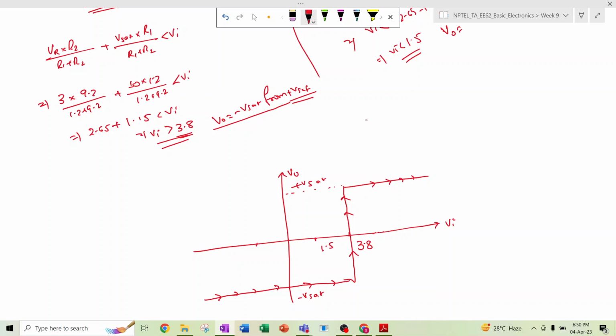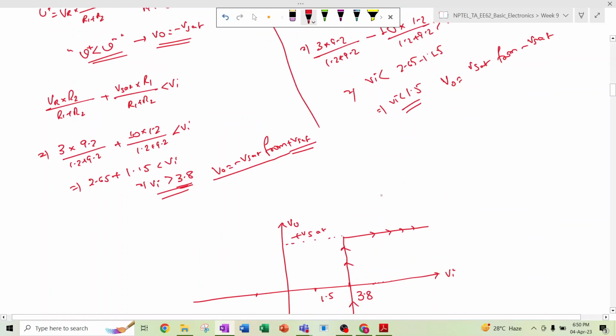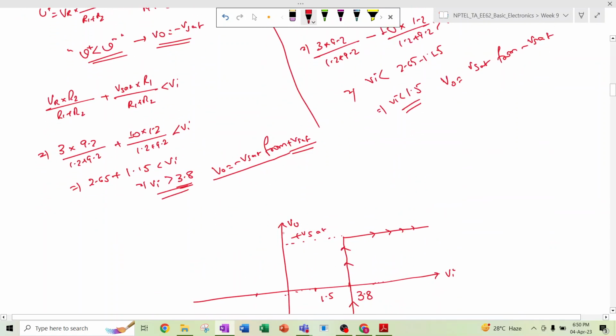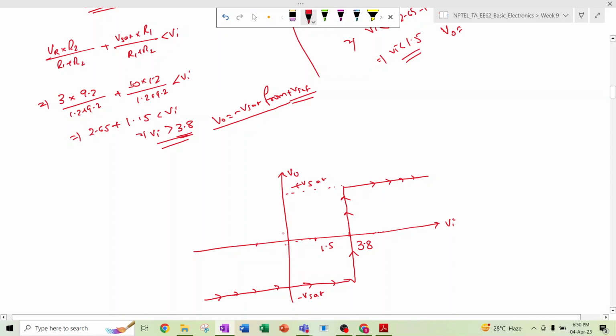If Vi is less than 1.5, in this region, then VO goes to plus Vsat from minus Vsat condition. Earlier it was minus Vsat, and after 1.5 it goes to...